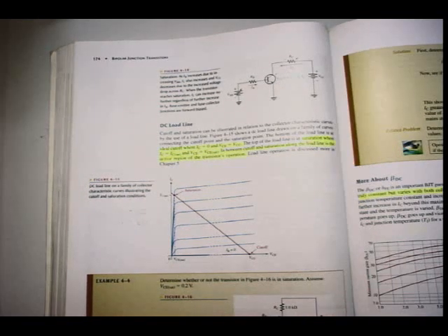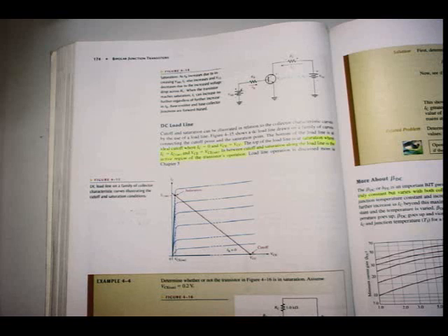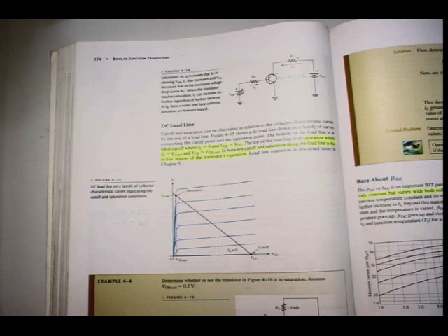We will discuss the load line in more detail in the next chapter, but you have to be sure that you understand the transistor being used normally as a switch and as an amplifier. So as a switch you can see cutoff and saturation. In between those two is the linear region, where I will use it for amplification. Just understand that so far. We will discuss it in more detail as we go along.